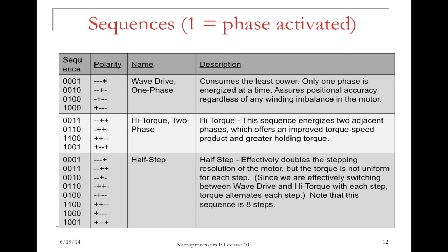And then you can see we have 4 bits here, 0, 0, 0, 1, and we have 0, 0, 1, 0. Each sequence has 4 bits. And these 4 bits indicate what should be the voltage supplied to that terminal. So let's say this is 1A, 1B, and 2A, 2B. That is to say, all these 3 terminals should be low voltage, and this one, 2B, should be a high voltage. So the polarity generated will be like this. So it will be like minus, minus, plus. That indicates the north, south directions of the magnetic field.